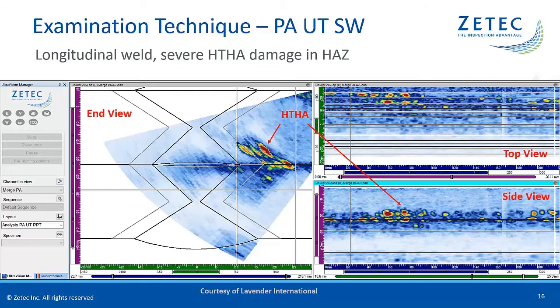Using a partial aperture of the large probe brings the beam exit point closer to the weld and increases the direct coverage. Also, the smaller active aperture provides more depth of field, which is more appropriate for detection scanning. First of all, we can observe a relatively high noise level on the data, higher than what we're used to see on data from generic weld inspections after manufacturing.